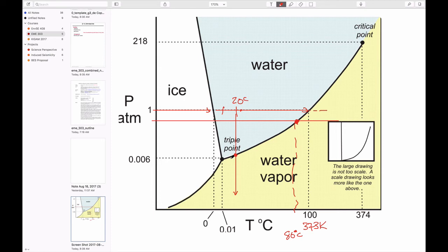But also on propellers. Submarines are designed with very big propellers. They almost look like the turboprops on turboprop planes. That's so they can rotate very slowly, because if they rotate slowly, the velocity of fluid going across them is small. The change in pressure across them is small, and you don't drive the pressure down so that you cavitate the water, turning it from liquid to vapor as bubbles, and as the bubbles implode, you can hear them.